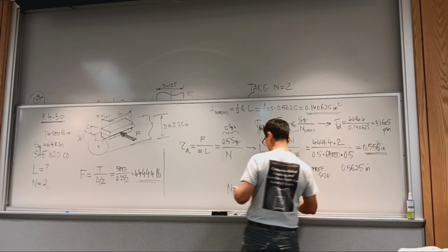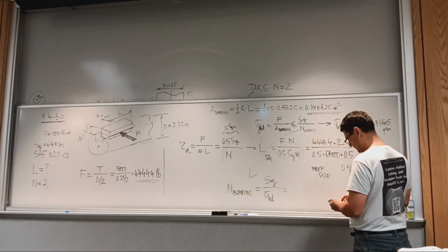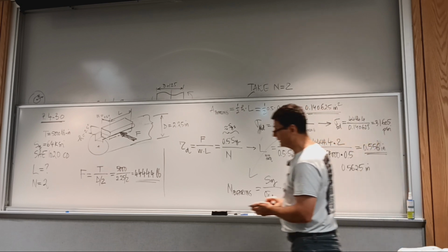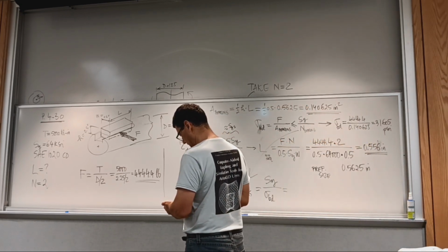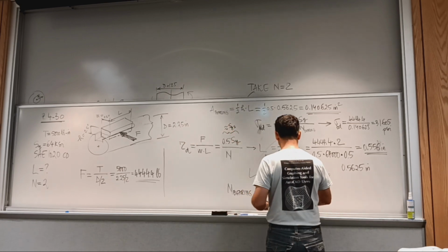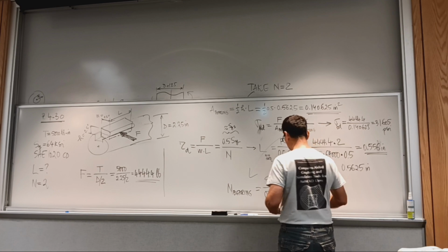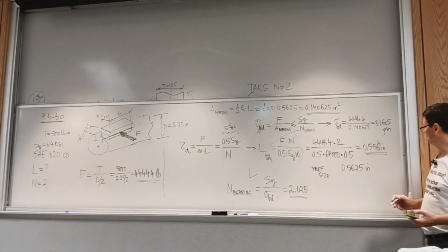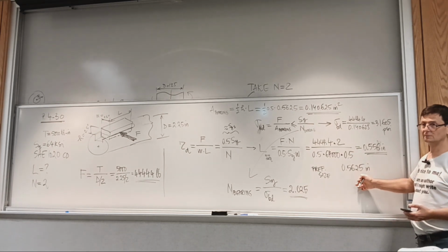I have the bearing stress, take the inverse, and then multiply by 64 exponent 3, and it gets me, as expected, a 2.025 design factor. It's slightly bigger than 2 because this went a little bit bigger. Does it make sense? That's why.